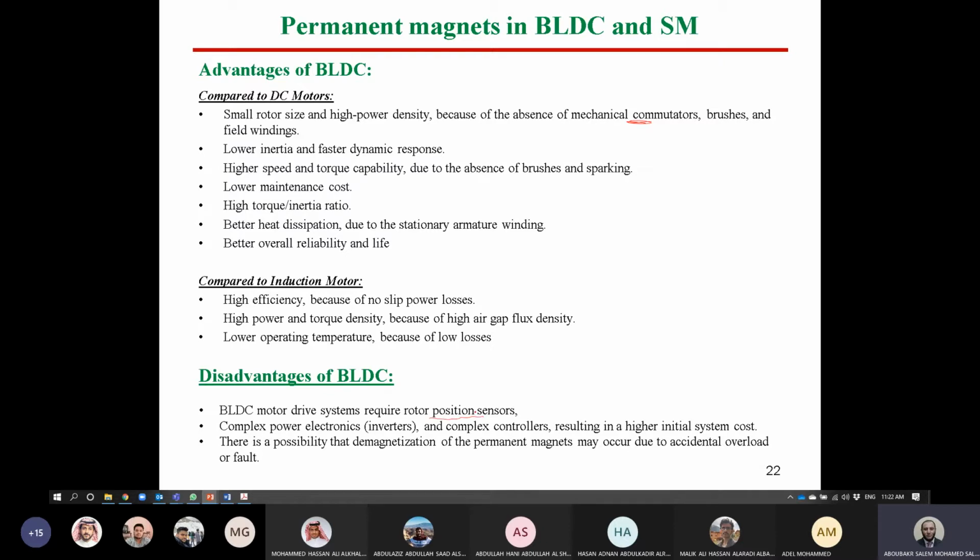We can just sense the current and voltage in order to control this machine, as in induction or any other kind of machine, where we have to sense voltage and current. So there is no need for a position sensor with advanced control techniques like model predictive control and direct torque control with sensorless. So even this, I can say, is a bit old because now we can work sensorless.